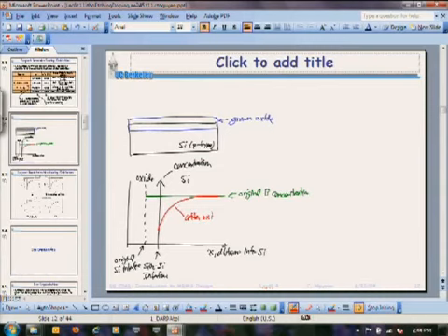So in the oxide, this is your boron concentration after oxidation. And your concentration in the silicon after oxidation is now looking like this. And so what are you seeing here? You're seeing that the boron has been depleted from the surface of the silicon.